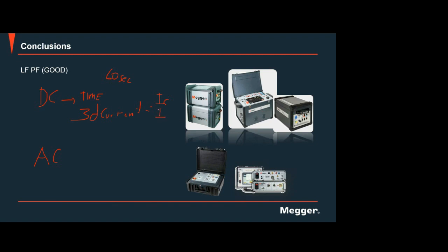Next, or at the same time, it is also doing the polarization. That is the alignment of the dipole. Okay? And the last current that we are seeing there is the leakage current, which is our concern. That is our concern. How much current is leaking in my insulation?